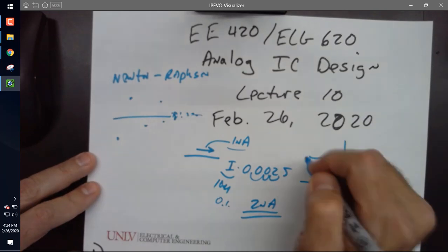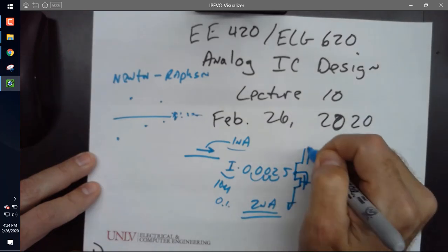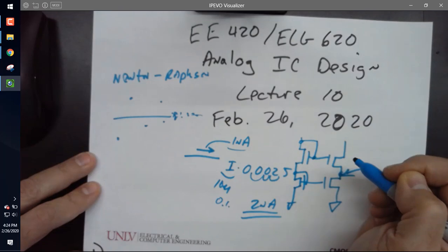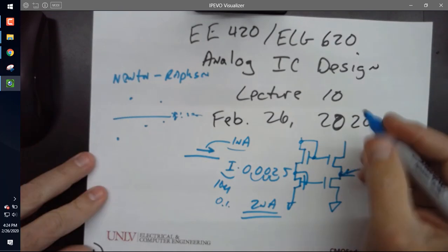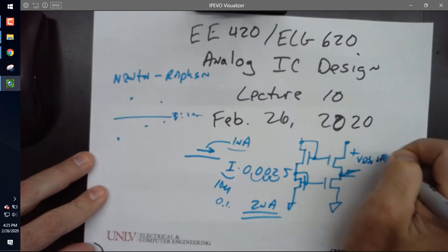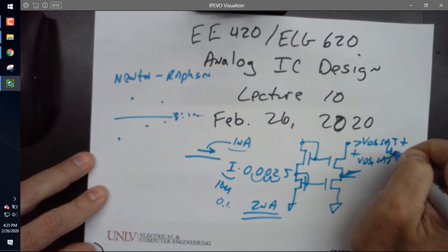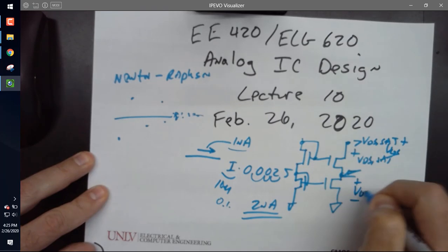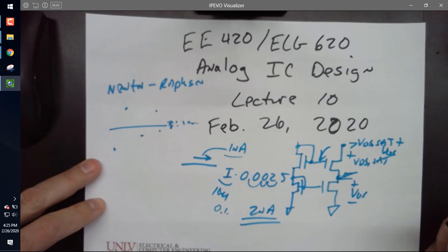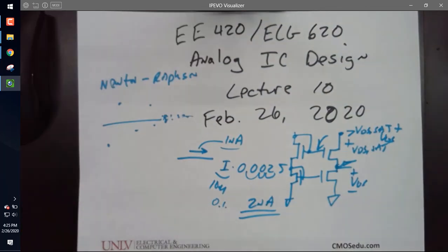But in our basic Cascode, which was this one, right? What was the drawback, the first drawback of using the Cascode? You need a higher VDS on the. Yeah, this needed to be VDS sat plus VGS. All right, which was across here, because what was that voltage? 2 VGS, all right? So then we said we're going to talk about the wide swing configuration.